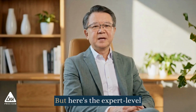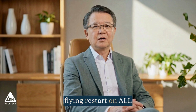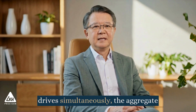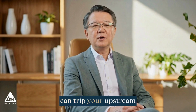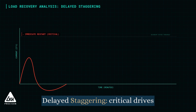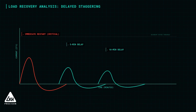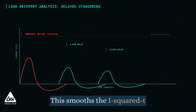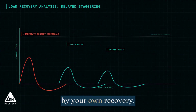But here's the expert-level warning. If you enable flying restart on all drives simultaneously, the aggregate inrush current, when they all restart at once, can trip your upstream breakers. The correct strategy is delayed staggering. Critical drives, like exhaust air fans, restart immediately. Secondary drives follow with 5-minute, 10-minute delays. This smooths the I²T inrush curve and prevents a secondary outage caused by your own recovery.